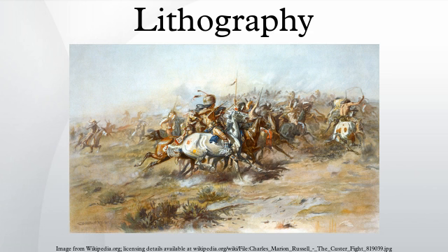As a printing technology, lithography is different from intaglio printing, wherein a plate is either engraved, etched, or stippled to score cavities to contain the printing ink. And wood block printing or letterpress printing, wherein ink is applied to the raised surfaces of letters or images. Today, most types of high-volume books and magazines, especially when illustrated in color, are printed with offset lithography, which has become the most common form of printing technology since the 1960s.